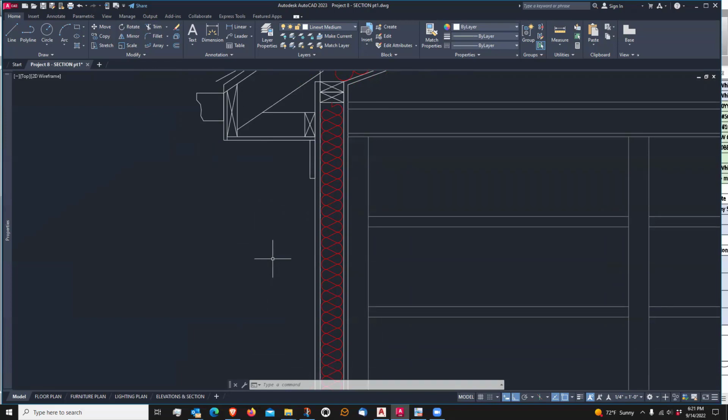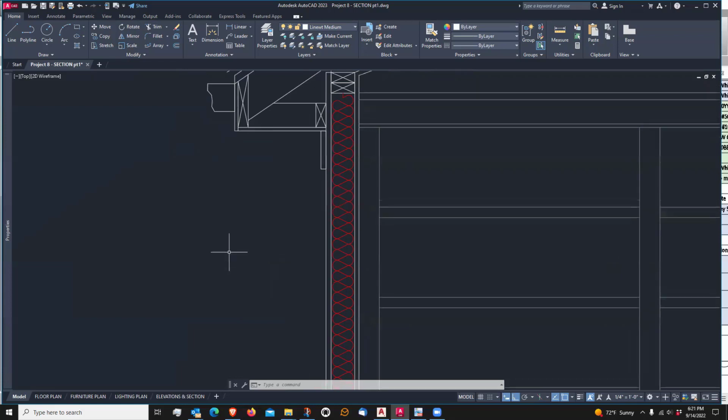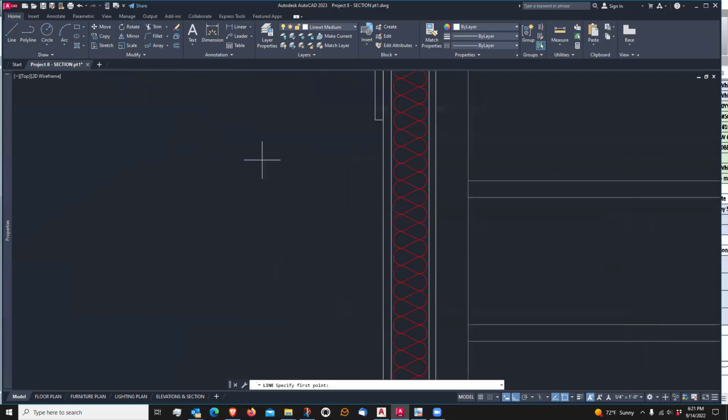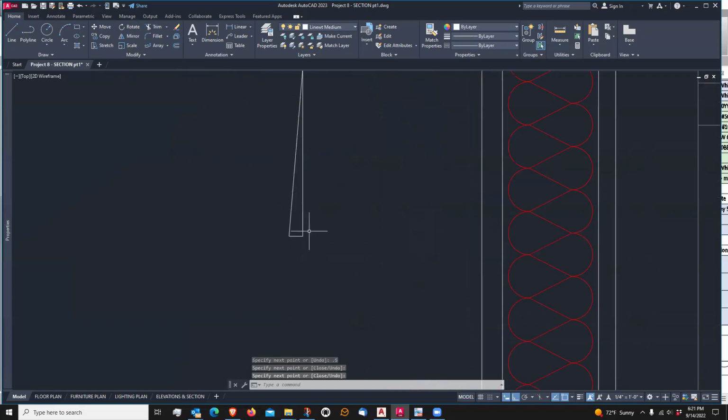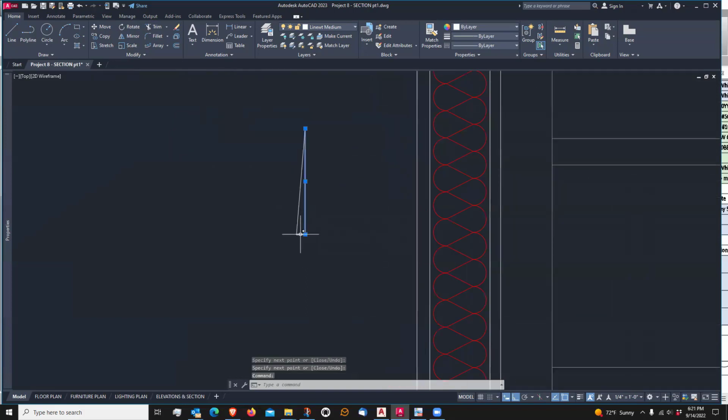So now let's get in our siding. Sorry. Okay, so our siding, I'm going to use the line tool here, and I'm going to draw a little triangle. Our siding is going to be 6 inches straight down, and then it's going to come out a 1/2 inch, so 0.5, and then it's going to go back to that start point. So these two lines here that I drew, the 6 inch and the 1/2 inch, those are just guidelines. Well, actually just the 6 inch is a guideline. I'll leave this one, so I'm just going to delete that.